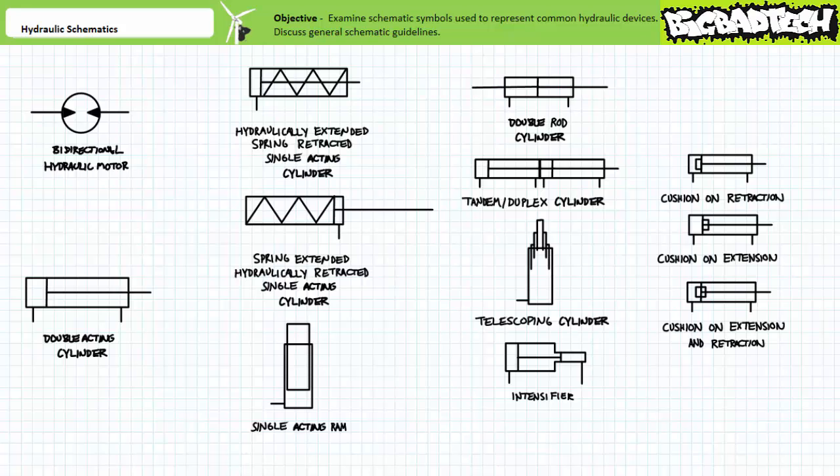Note, single-acting cylinders sometimes incorporate a drain port on the opposite end to keep this space from being obstructed by any accumulated fluid that happens to leak past the piston. The schematic symbol may or may not indicate this vent port.